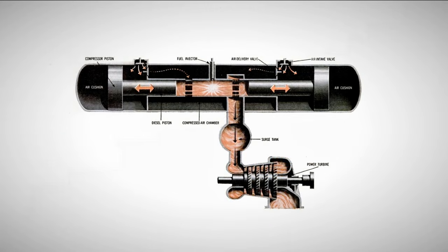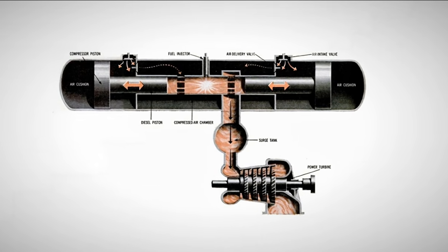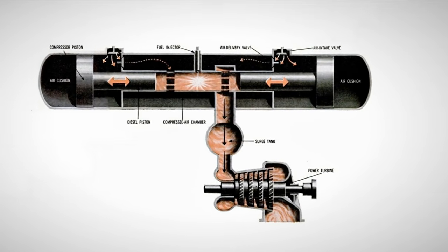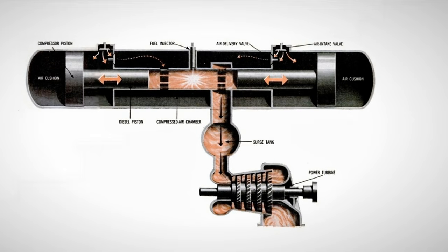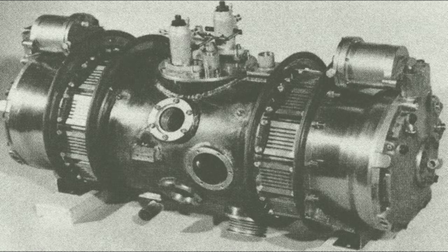Most often, a two-stroke free-piston diesel engine is used as the gas generator for such hybrid engines. This power plant, in general, can also be called a free-piston turbine engine. Due to the broad scope of the term free piston, many engine configurations fall into this category. However, the term free piston is most often used to refer to a linear engine that lacks a crank mechanism.